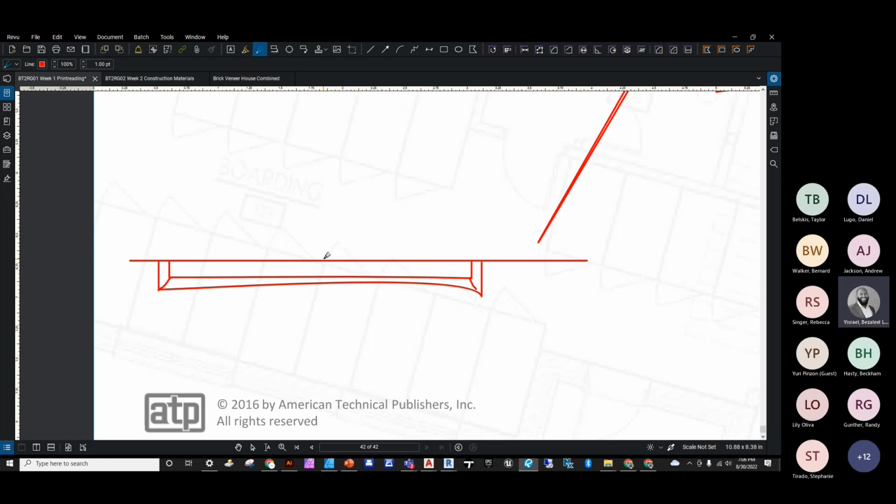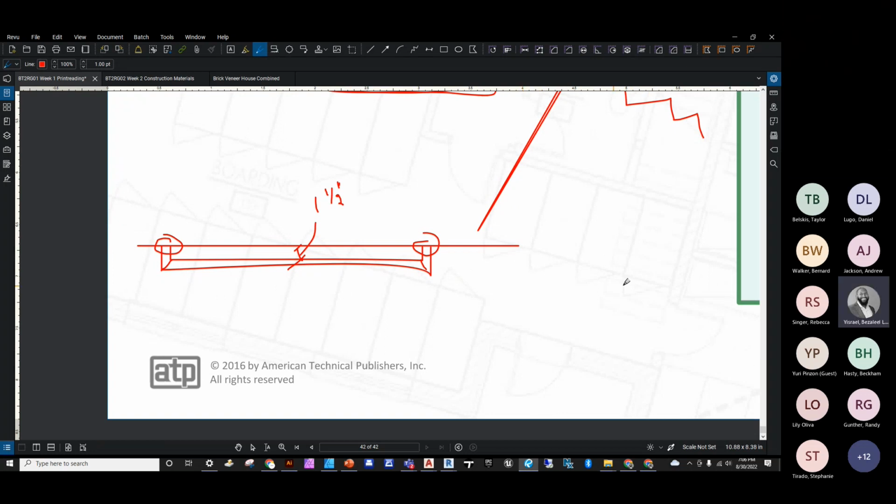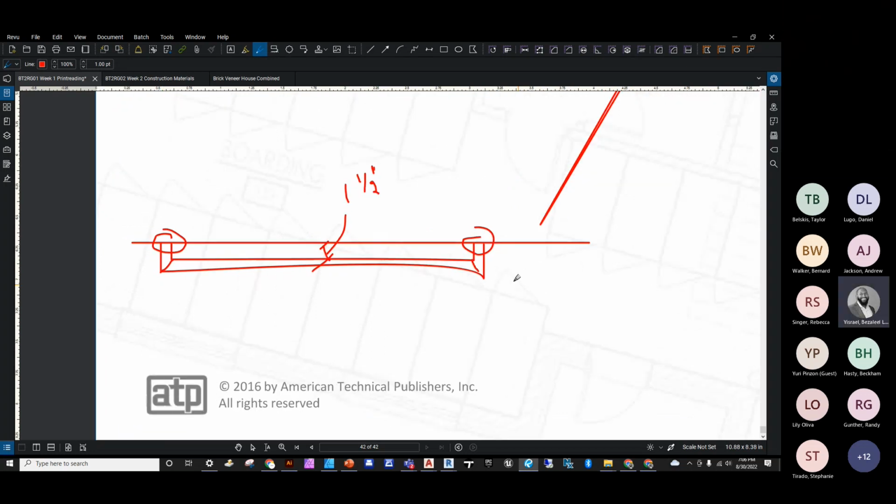Understand. Thank you. You're welcome. And then here in this area, it will be that 1.5 inches we mentioned. That should be a minimum clear space so your fingers can just grab in there comfortably. And then here's our return areas going back into the wall. Okay, so in your instance, you could probably just miter that end of it, do another piece, and then either screw it, glue it, and bring it back into the wall. Understand. Okay.